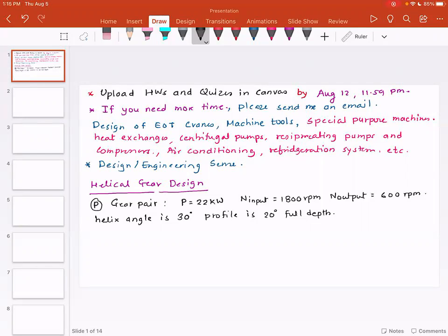It can work for worm gears as well. However, for bevel gears, it is always recommended that you replace the entire gear pair. So that is something that you should keep in mind.